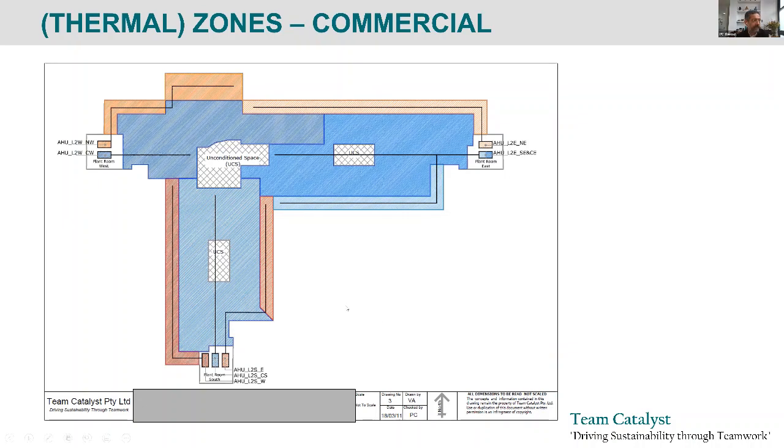The people in the east would be warm in the morning. The people in the west would be warm in the afternoon. And the people in the center would always be too cold because you're designing for some average air conditioning load. Okay. That's the reason why air conditioning engineers divide up blocks into perimeter and center zones, or interior zones, if you wish. So when you do zoning, you need to think about that a little bit carefully.